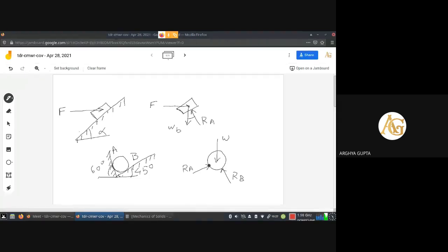So that's how the angles can be calculated easily if the angles are given. If we extend the thing, then with vertical also this angle will be 60 degree, and this angle will be 45 degree. Hence that force analysis can be made. This can be split up into horizontal and vertical components. Then by means of equilibrium, we can solve the numericals. So this is the basic idea of the free body diagram. That is how the free body diagram is being drawn.